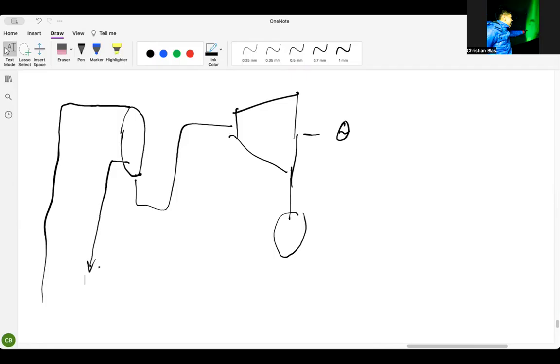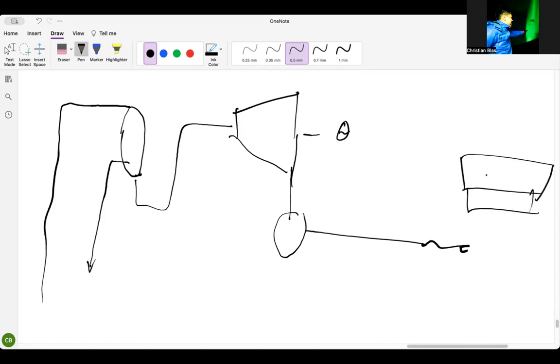Okay. Then after that, the turbine generator goes to the condenser, and then the condenser goes to a circulating water pump that transports to the cooling tower. So after this, you have this that goes to the cooling tower. Okay, so this one goes to here. Then it is also re-injected to the well. Okay, this is for a single flash. So if it's a two stage flash system, we have another flash here, just another one. And then that would be the two-stage flash conversion. Okay. So this is the schematic.